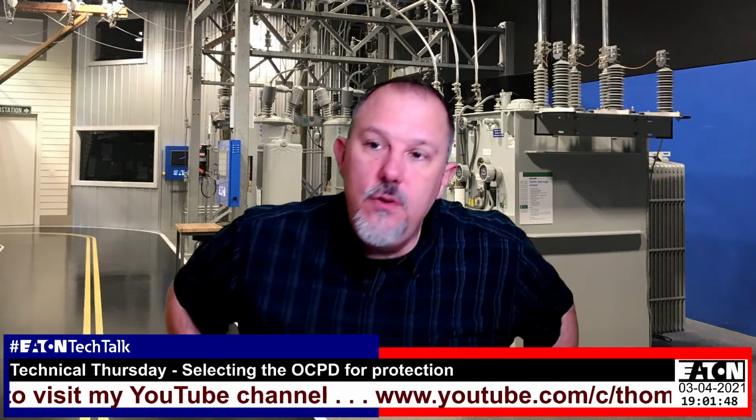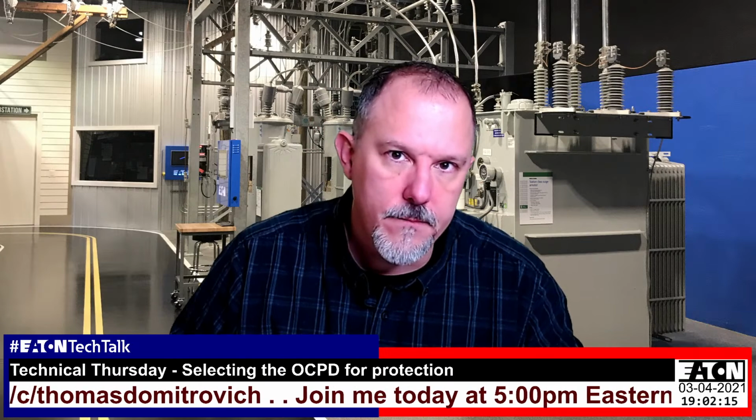My opinion on this is I like 240.87, but I think it needs work. Here's where my thoughts are. 240.87 and 230.95. 230.95 is GFPE protection of equipment, service equipment, and 240.87 is really there for the electrical worker.